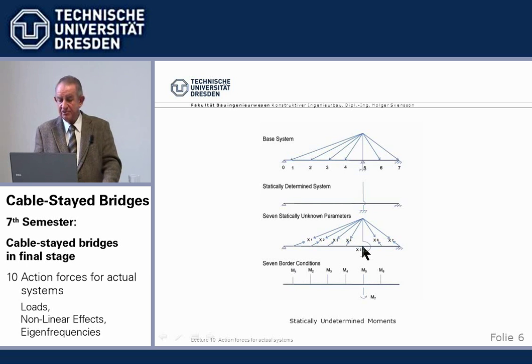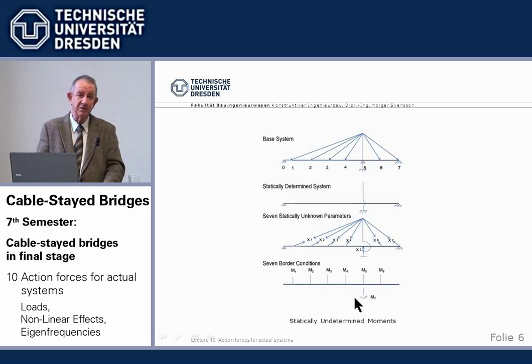Then related to the support, of course, is the beam moment at the support. And finally we have one free, thank God, the 7, and that we use to determine the tower moment. So, with this set of statically indeterminate ones, we can define all beam moments: the beam rigidly supported on its supports, plus the tower moment.